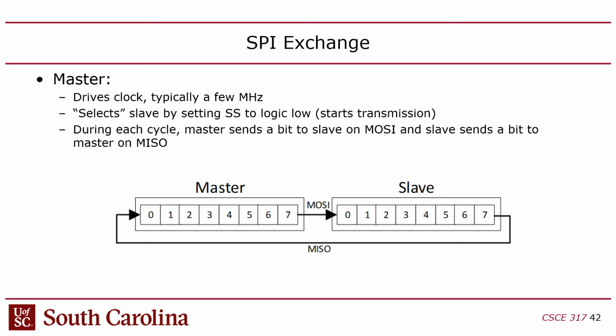Well, the problem is that this actually doesn't work for programmed I/O, because, as you guys remember, in programmed I/O, I have to send the address out before I do the data part, right? I can't do this swap, because this swap implies that I know which registers I'm exchanging before the transaction even begins, which is absurd. There's no way to know that, right? So no one actually uses this shift register model in practice.